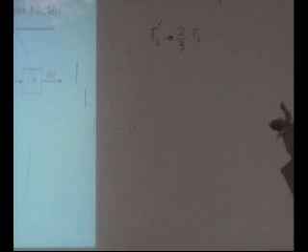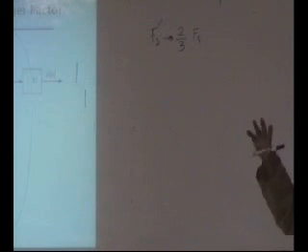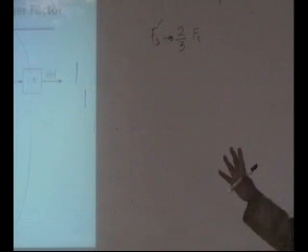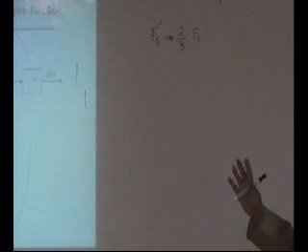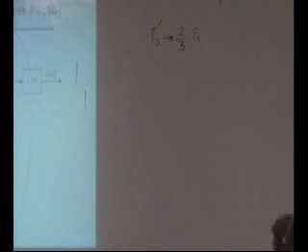The good way to do this is to always increase first, because while you are increasing the sampling rate, you don't lose any information. So always increase the sampling rate and then decrease it by 3.